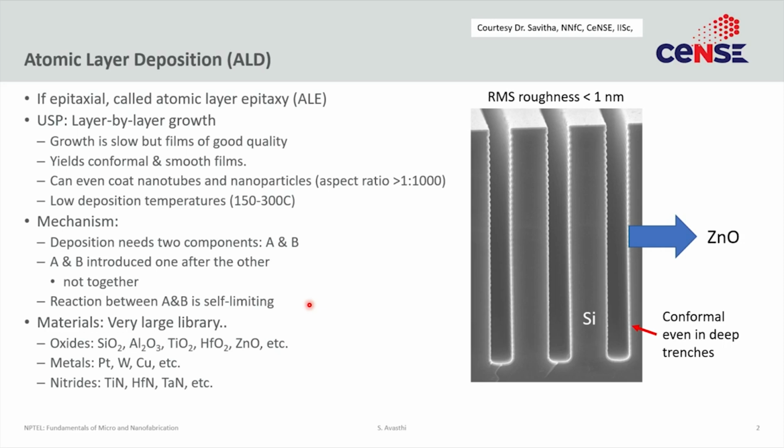If you remember the lecture on native oxide growth, where we discussed growth of silicon nitride on silicon by flowing nitrogen, we realized that cannot happen because nitrogen is a very stable and inert molecule and it requires very high temperatures to break nitrogen and form a silicon-nitrogen bond. So similarly, growing nitrides with nitrogen is not possible. However, just like in nitridation, we were able to introduce ammonia, a more reactive form of nitrogen, and react silicon with ammonia to form silicon nitride. We can do similar things here. So we can do ALD with ammonia gas, and that allows us to deposit nitrides.